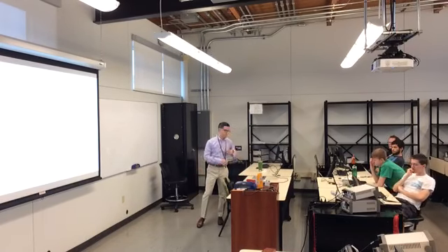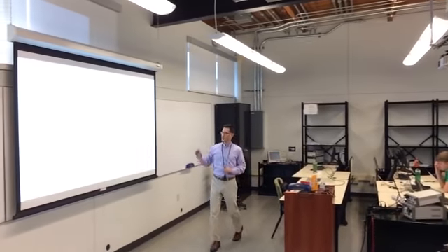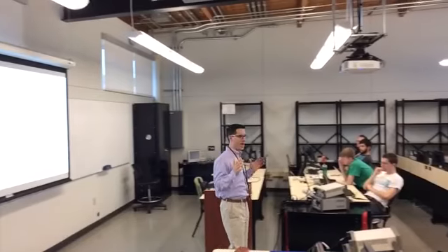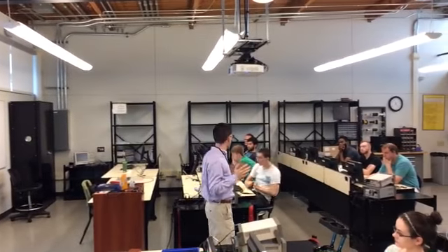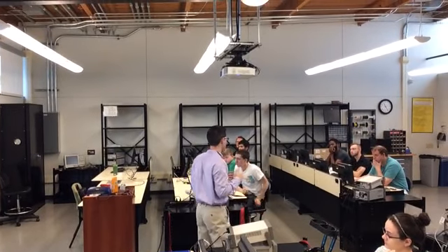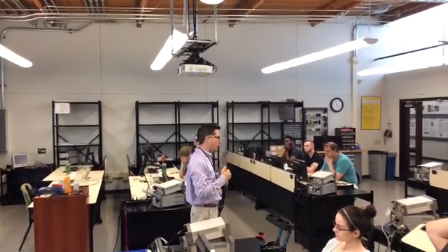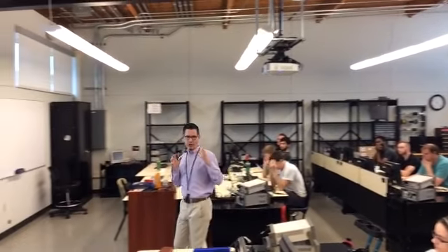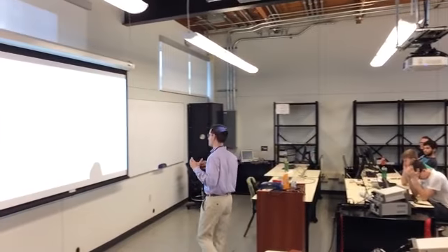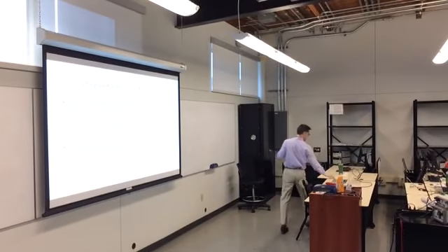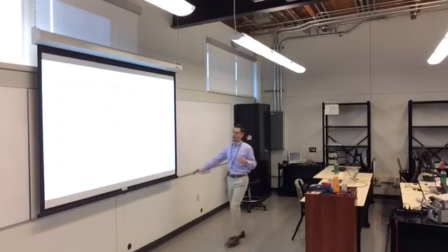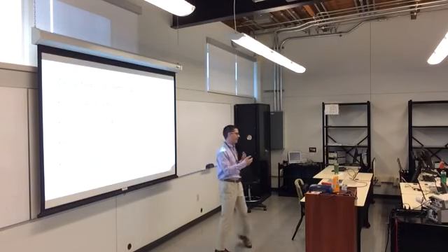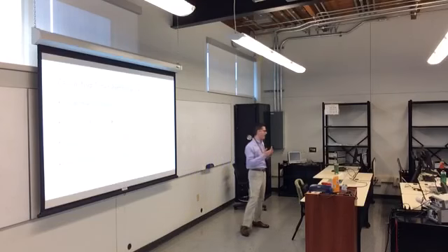Now, some of this stuff is fixed. Some of this stuff can be modified. The maximum value of your timer is generally fixed. It's a 16-bit timer. You don't have any extra bits. You could cascade your timers together, but in general, you're going to have a single timer, and it's fixed. When we have this equation here, remember that the frequency that drives the clock is not fixed. It is modified by a prescaler.